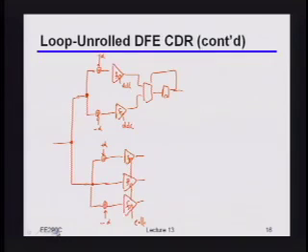Okay? So just to make sure it's clear, as we said, this thing where you have the 0 threshold, that's basically something dealing with a clock pattern, right? So that means that you have something like 101 or 010, right? That would sort of be a clock pattern, right? Okay, for this upper guy over here, where I've shifted the threshold to be plus alpha, what kind of transition is that? 110.